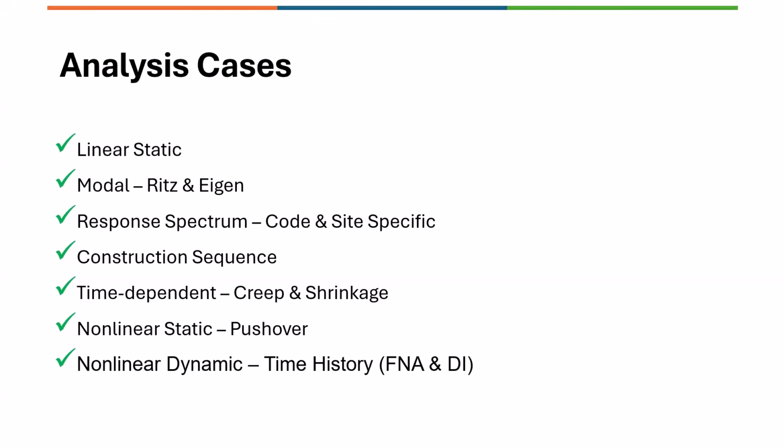Okay, so construction sequence can handle elastic as well as nonlinear, time-dependent properties like age of the concrete in your sequence case. So that is possible. So it is a nonlinear case. When enabled, that is also considered. We have nonlinear static, for example, a pushover analysis, which can be used to study the response of the buildings.